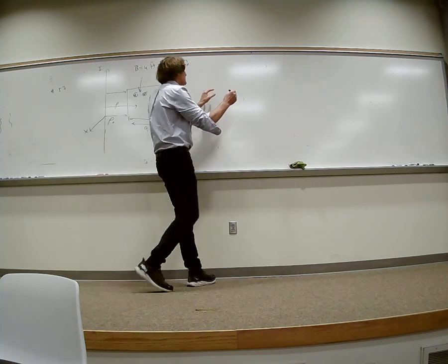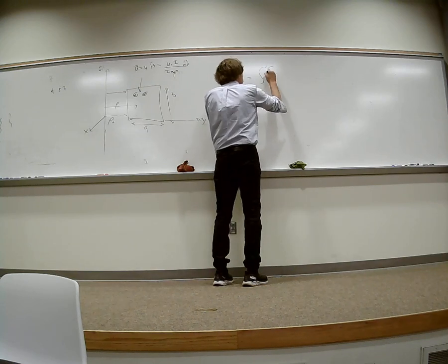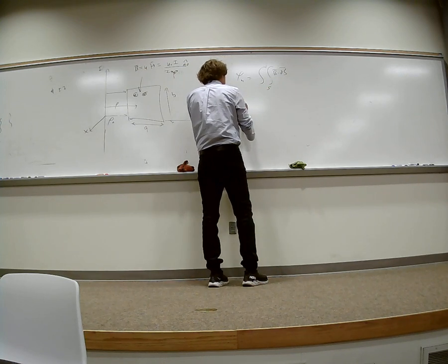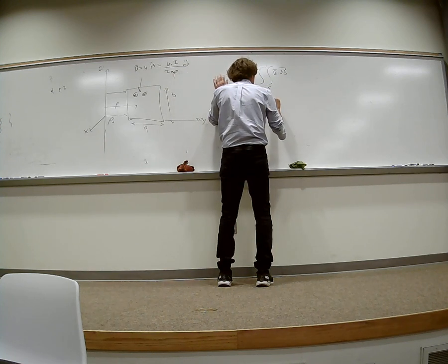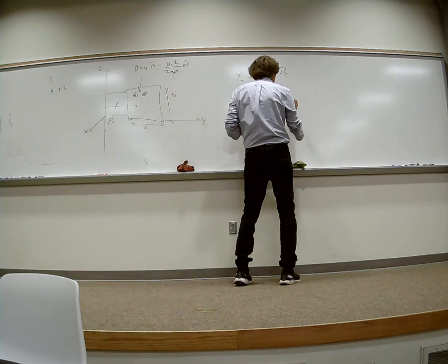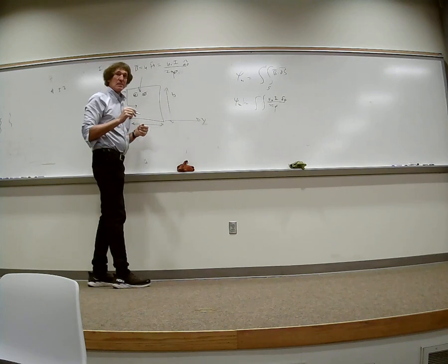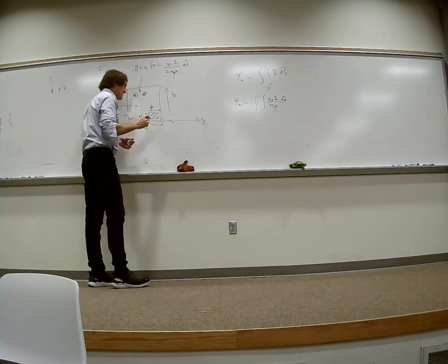And the flux, this is the symbol for magnetic flux, will be simply the integral of B dot dS over the surface. That's all it is. So the magnetic flux will be a double integral. Here's our B field, mu 0 I over 2 pi rho. You can put it in the A phi direction or minus AX, it doesn't matter. It has to be dotted into dS. Does everybody follow me on this?